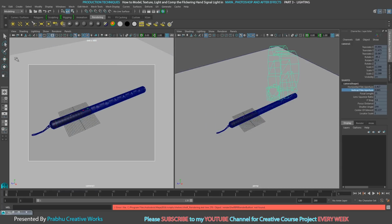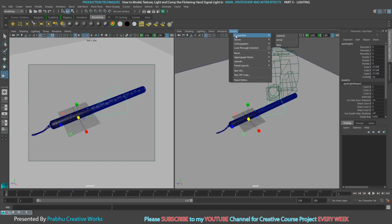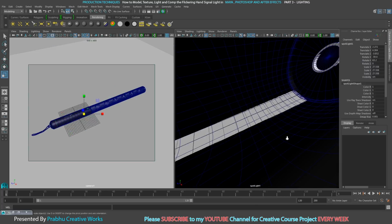Okay, first of all I want a key light, so click in rendering spotlight, and it will automatically be created on our grid. Scale this one big. Now I want to see through the light. Select the light, go to panels, perspective, look through selected. So that means you will be able to see through the light. So I will move the light.